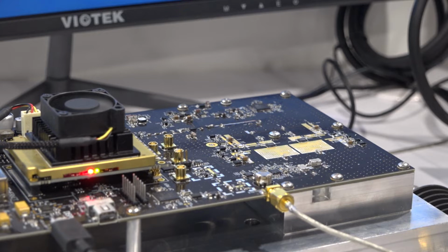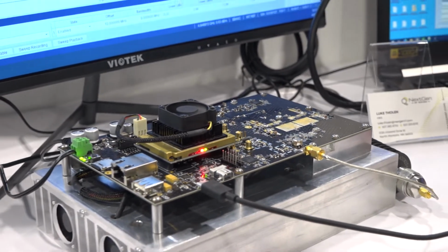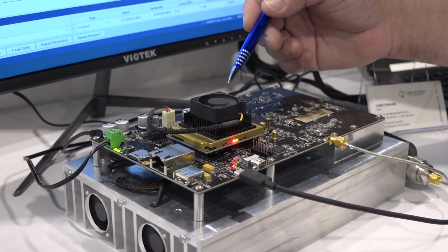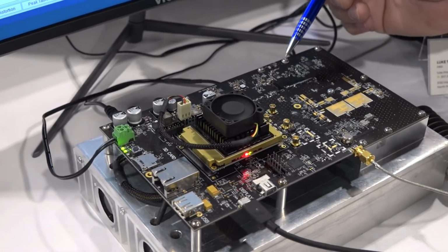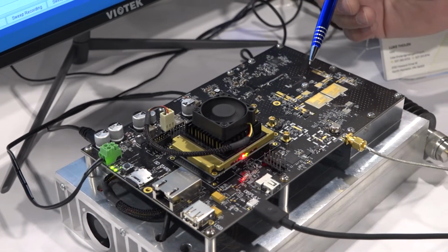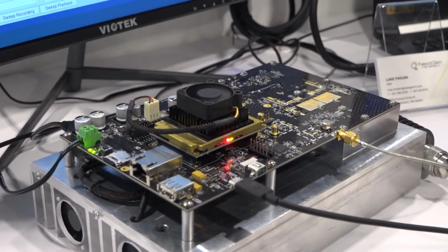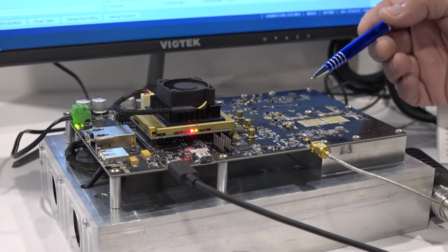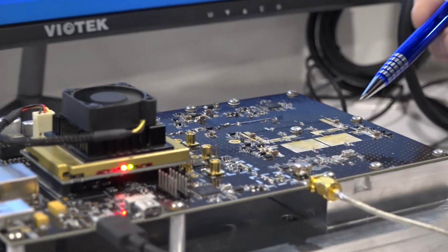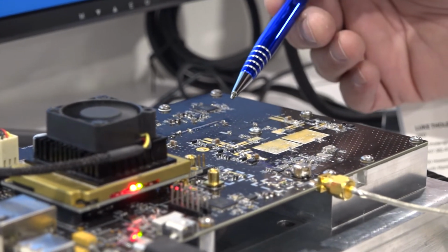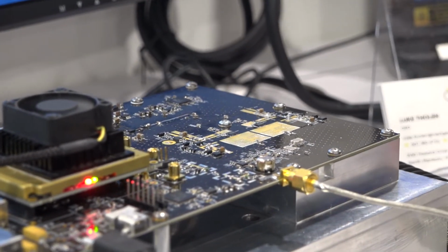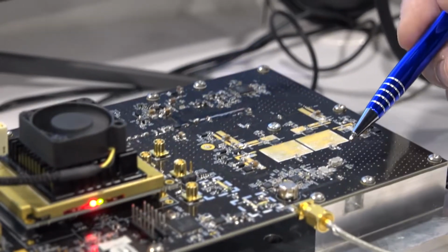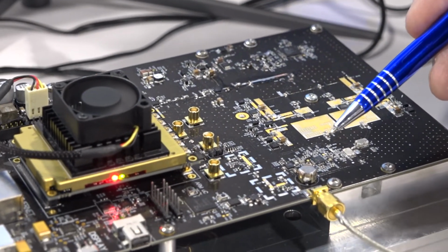On the transmit chain, we have 3 stages of cascaded amplification. We have a pre-driver from Gorilla RF, a driver, as well as a final stage amplifier that's designed using high performance GaN transistors from Wolfspeed. The final stage amplifier is designed in a balanced hybrid configuration, so we have input hybrid couplers as well as output hybrid couplers. That signal then goes through a directional coupler and then out through the circulator to the